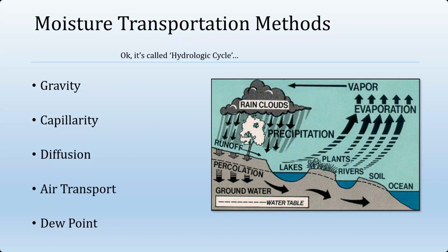Water can actually defy gravity and traverse upwards and laterally. I've seen great examples of capillary water action in above grade wall sections, for example, where entire steel framing had been virtually rusted out. So it's certainly something to be considered. We always want to break that capillary action, and typically we can achieve this through the use of a drainage mat, which we'll discuss also in this program.